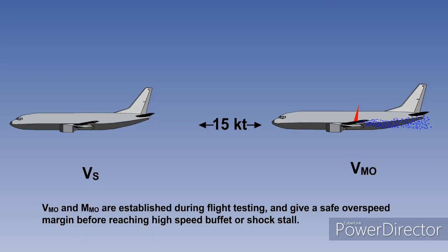These maxima give a speed margin into which an aircraft can momentarily overspeed and be recovered by the pilot before any undesirable effects occur. This lesson concludes the series on stalling. The problems incurred by shock stall, such as tuck, loss of control effectiveness and instability, are covered in detail in the lessons on high-speed flight.